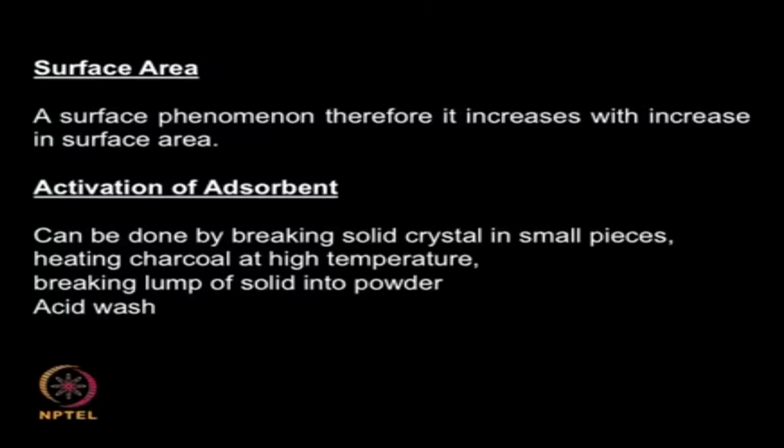So there the temperature is raised and the tar is completely burnt off, so that the catalyst again gets regenerated. So use of temperature is very good for activating your adsorbent, assuming that temperature does not affect your adsorbent. For example, if you use very high temperature, there could be sintering taking place. Sintering is nothing but agglomeration or conglomeration of smaller particles of the surface into larger particles.